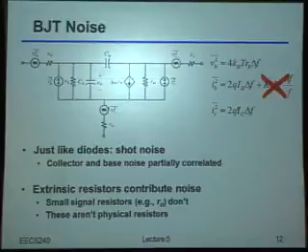So the last very important point that I want to make sure you get from the slide is that I added in these noise currents to model what was physically happening with the diodes. But notice I have no noise current whatsoever associated with this output impedance. In general, you have to be very careful to never add noise currents due to small signal output impedance elements, because you have to remember that noise comes from the physics of the operation of the device. It's related to charges, how much charge is present in the channel, or charges jumping across barriers, and so on and so forth.